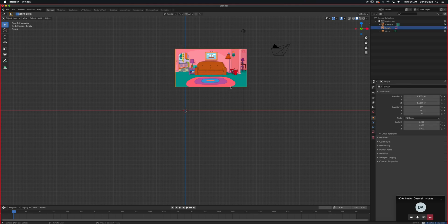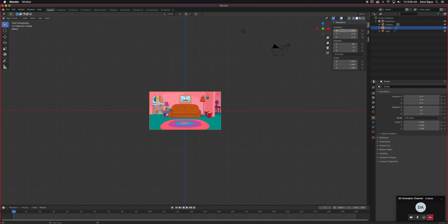All right, so I have the photo selected. I'm gonna press N, it's in numbers, to get our transform item right here. So there's your location. It has a value because I just dragged that in there. But if I click and drag X, Y, Z together, I can press 0 and just center that in. It has no location value. It has no scale value.